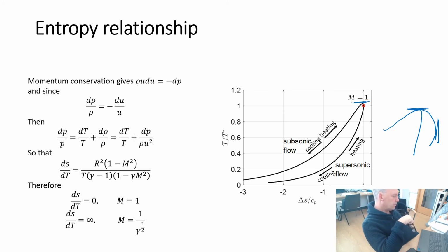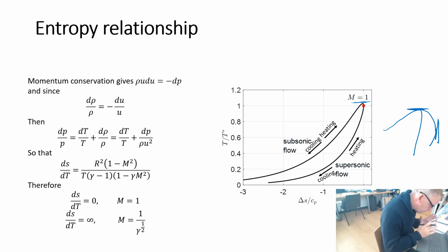but Chapman describes it in terms of the speed of the flow after the shock, and other people describe it as a state in which the entropy is maximized. They all give the same answer.